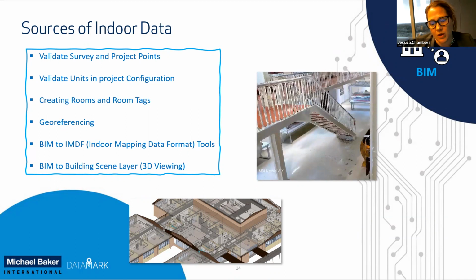Okay, so we're going to start with understanding where the data comes from and how it's created. Predominantly, we'll use Revit as a source to populate BIM data into ArcGIS Indoors. All right, that's where the information comes from. So a little bit behind the curtain with respect to Revit data creation: Revit creates three-dimensional objects on a screen in space, and it's a virtual model. Within those assets, we do have attributes associated with them. This can be generated from what we call families. Okay, so families of information.